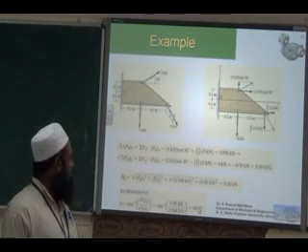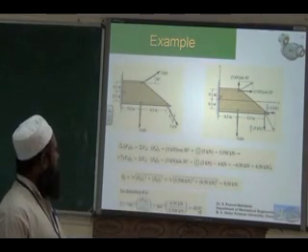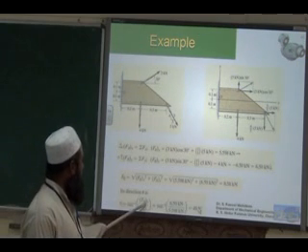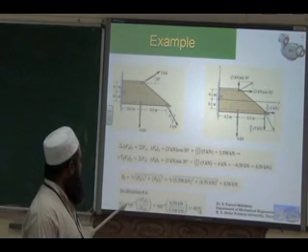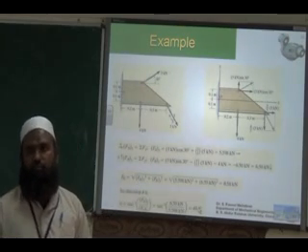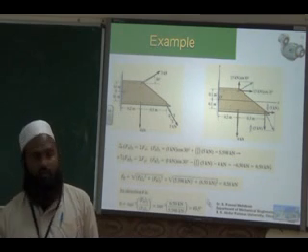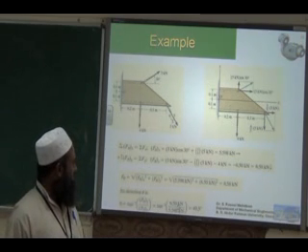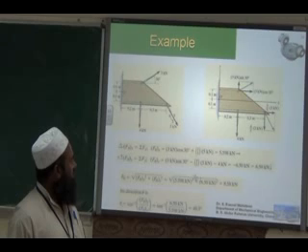And its direction can be obtained as 49.3 degrees. The direction of the resultant force, theta, will be tan inverse of FRy divided by FRx, the resultant y component divided by the resultant x component. So that will give you the angle of your force.